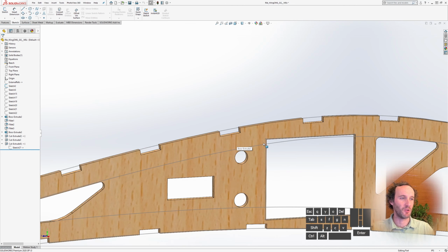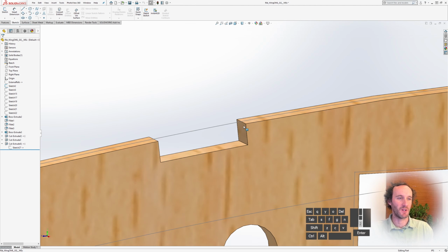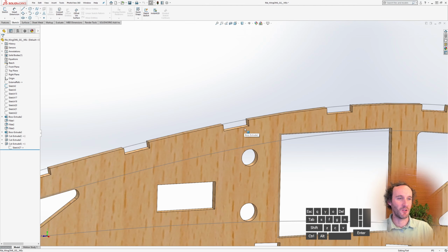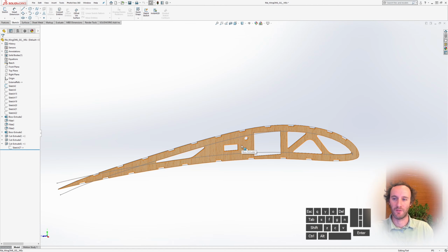So in practice, with the balsa wood stringers, if there's a slight gap or overlap as you put them in at an angle, they just sort of crush into place, and any gaps get filled with glue. As long as the stringer's not coming in at like 30 degrees or something like that, they end up fitting pretty well.